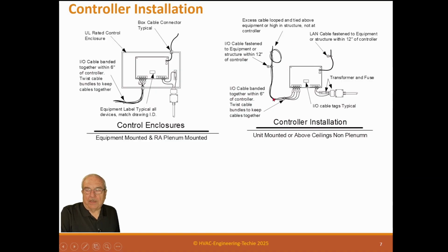And the one thing about it, when you've got a controller like this, you need to leave a little loop for some extra wire. So if we have to replace this, we can take it off and move it around a foot or two. It doesn't have to be very much, but a little bit. Never stress this to be tight.